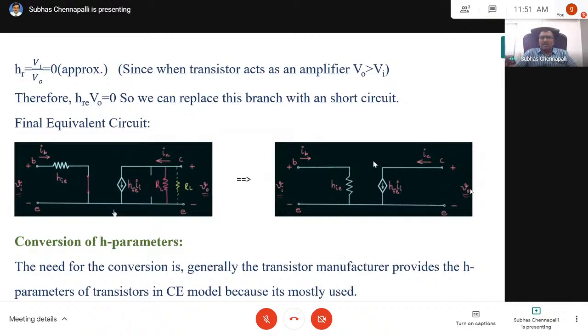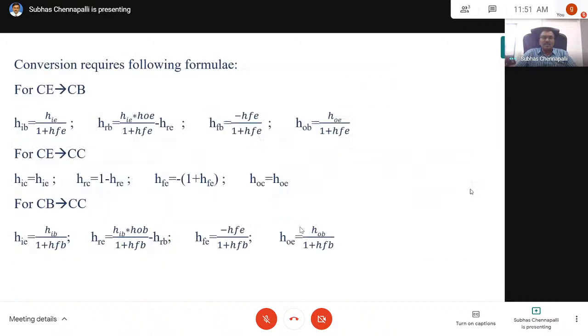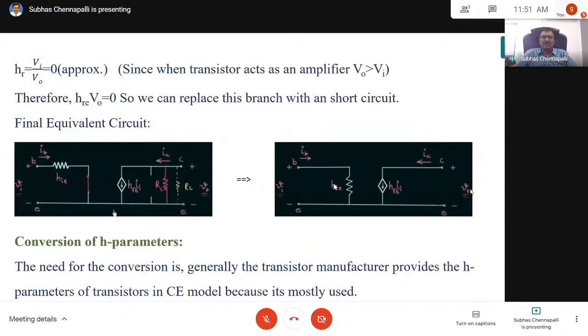So your H parameter small signal model is this one, and applying this you can easily do analysis of transistor amplifiers for small signal, and your work will be much less than when you consider the full H parameters. Now you can do on the same lines what we have done. You can arrive at all six parameters. Or you take those six parameters and substitute the approximations there. But it is better you do it the fundamental way and arrive at the formula.